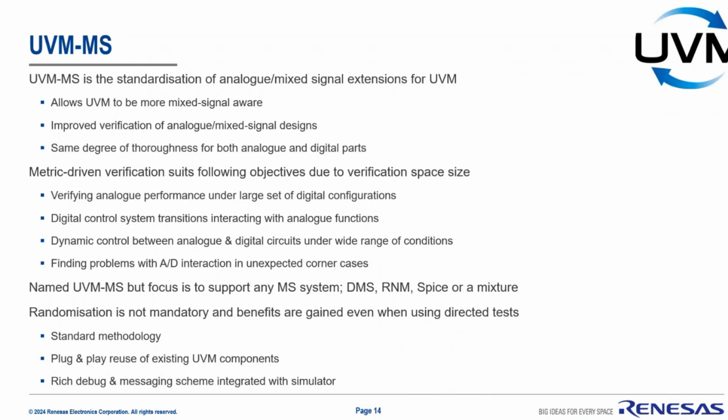But the idea behind UVM-MS is to basically allow constrained random verification with these three pillars of stimulus, checking, and coverage, and a standard way of doing it to be extended into the mixed signal space. So it addresses the optimal partition of verification code between the different engines, the co-simulation of the analog solver and the digital event-driven engine, and where to write the different parts of your environment for the most portability and reuse between AMS and DMS. It's built upon expertise from UVM and the AMS fields.